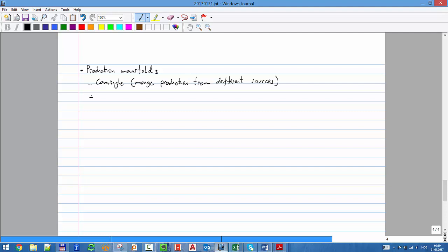Also, something that is important is that we want to test the well. Okay, remember we want to know how much each well is producing, and there are many reasons for that, but one of the things could be because the ownership of different reservoirs or of different sections of the reservoir is changing. Okay, so you want to know the share of each partner, so you want to be able to test the well. Okay, and testing the well has different purposes, but you can use it to determine production shares.